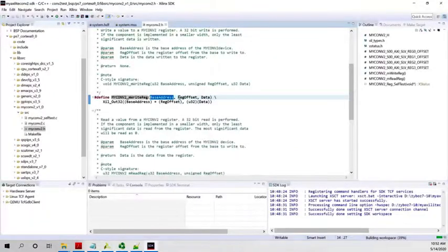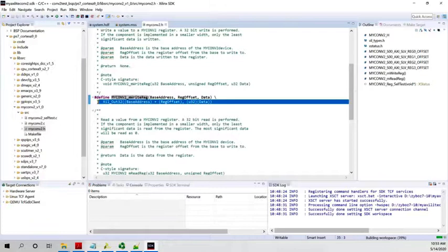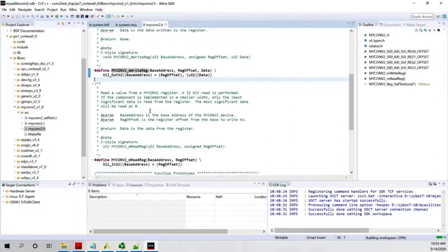So we need that, of course. And then you need the register offset, 0 for register 0, 4 for register 1, 8 for register 2, and so on. And the data that you want to write. Okay, again, this is just a function that is essentially this function here, this particular block. Because look at this block here. This block is already the most basic function actually, which you can use no matter what. It includes already the base address, but now of course you have to add here the offset and then provide the data. And that's for writing, right? And another one is for reading.